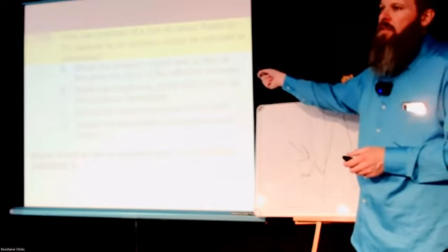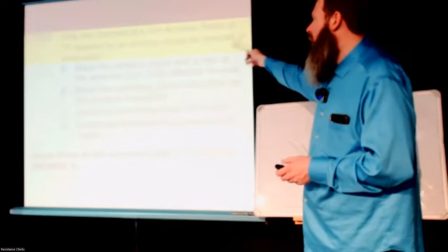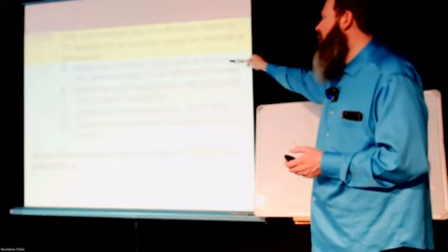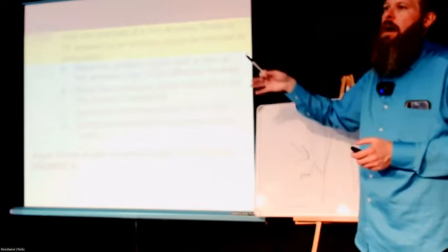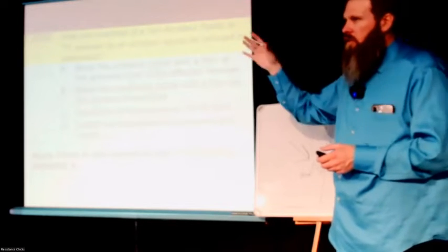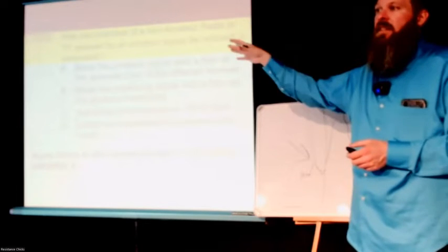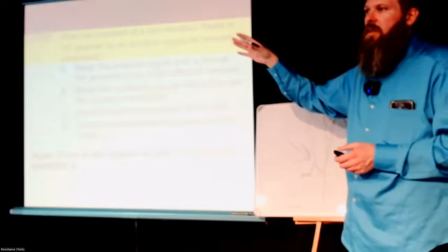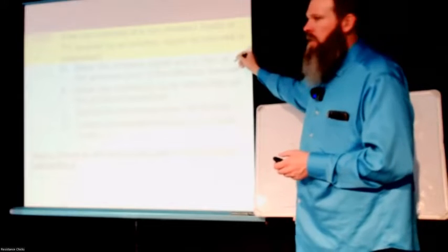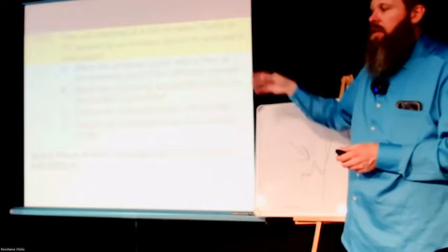So this isn't at your house, this is at your neighbor's house whose non-amateur radio, whatever kind of radio it is, you put a filter at their antenna to stop the frequencies from your ham radio getting in. Remember, your ham radio is just so strong, their equipment is so poor that it can't reject the ham radio signal. So you put a filter in there, a circuit tuned to the specific frequency so it blocks that, but it still allows whatever they're normally trying to listen to.